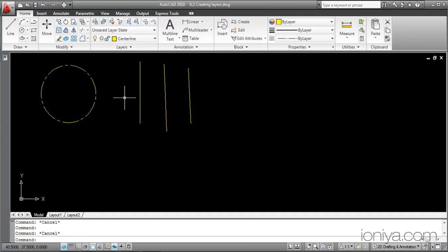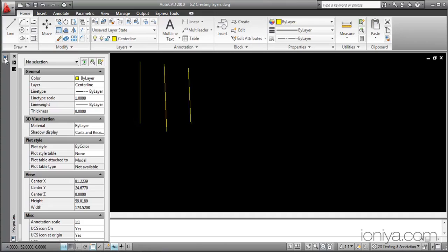Now we can see the line type is visible clearly, but the line still appears to be continuous. This is because we have only changed the scale of the circle and not the entire layer. Let's change the scale of the entire layer. Take your mouse pointer over the Properties palette icon, click on the Line Type Scale field, type 8 and press Enter.